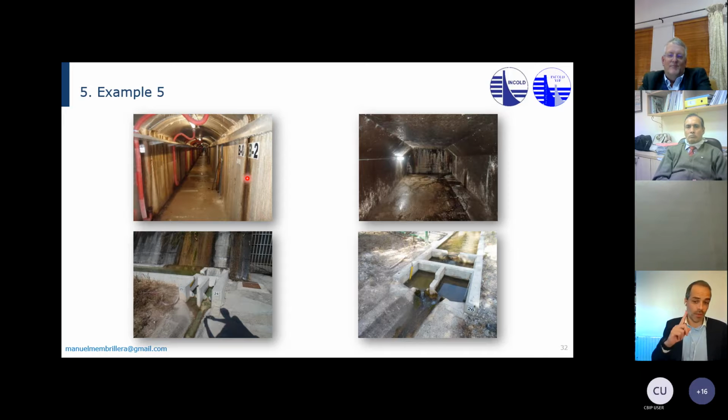They were not trustworthy because they were anchored to this precast concrete and they were not in touch with the actual RCC concrete behind. So what we did, we had to drill and make sure that our joint meters really went into the real concrete of the dam, so that we were measuring openings and displacements of the joints in a real manner.